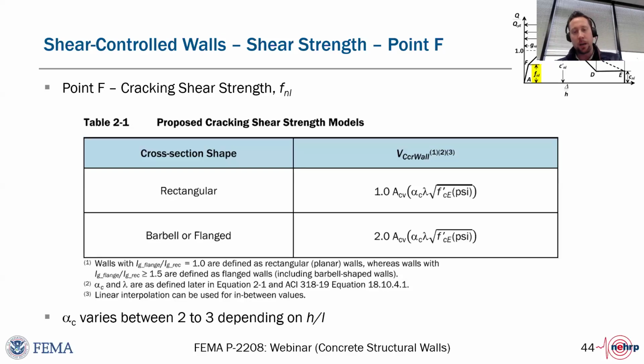That general statement would apply to walls. So generally speaking, if you have adequate development, then you are good. And one of the criteria for conforming walls in those bullet points is indeed also adequate lap. And all that means is that you're meeting ld. You don't actually need to go ls, and you don't need to extend beyond the critical section like ACI 318 says. You just have to meet ld. So the answer would be yes.